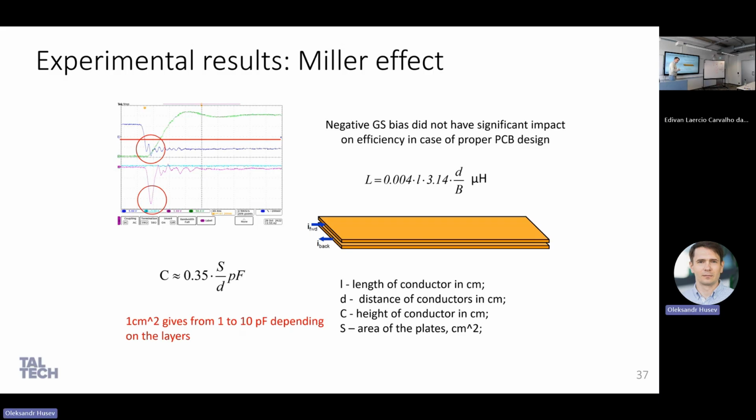If you put this overlapping on the first and second layers that have minimal gap, it will be about 10 picofarads, which is actually comparable to what you have in data sheets. Which means that, okay, it's a stupid mistake if I see that in a design, but if you add, like, drain and gate overlap, it immediately kills your operation. Just on this bit. Clear?